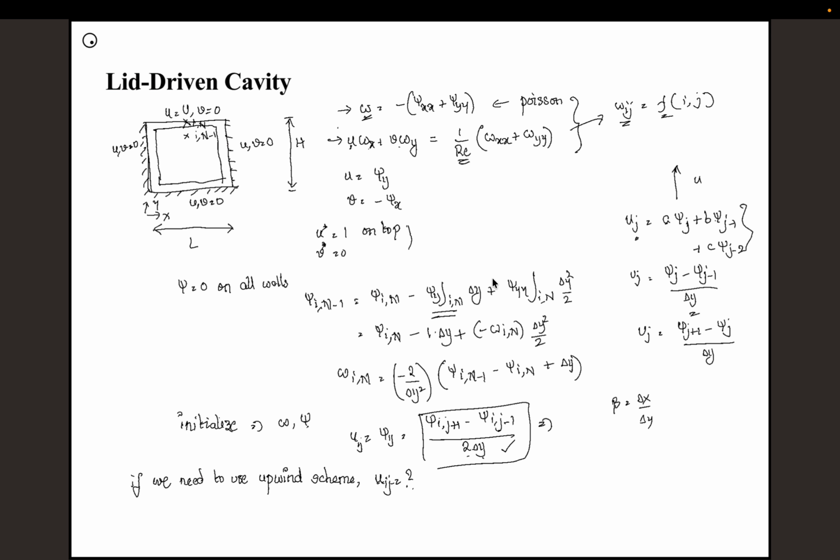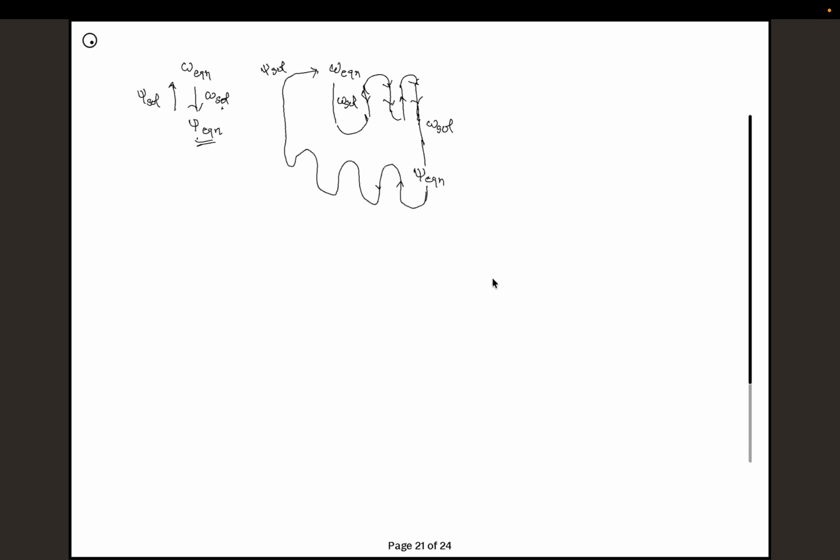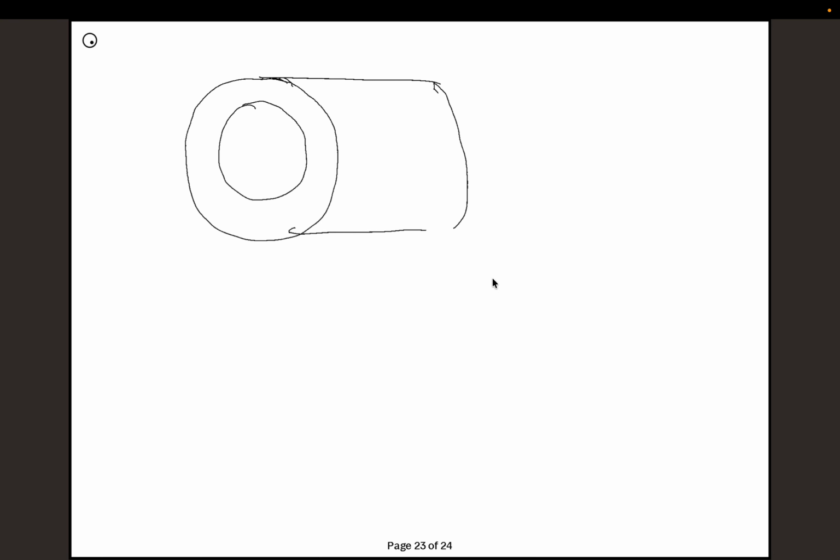Here, all you have to do is write your corresponding extension. But again, there are other challenges with respect to the mesh. All the examples that we are referring to up until now are rectangular things. Here we are assuming that the mesh can be done in some simple ways. But when we have a complicated geometry, then you have to come up with some functional form where you can map this space. For example, instead of solving this problem, let's say I have this problem. Instead of a parallel plate channel, let's say I'm trying to solve for an annular flow.